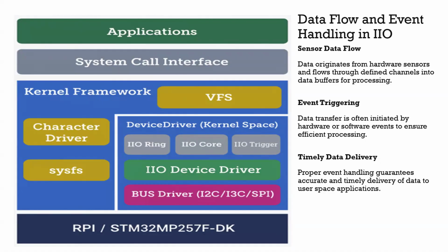One question here. Is the character driver also provided by the framework, or do you have to write and plug it in separately? Yeah, it's provided by the IO driver in this case. But if you want a very generic character driver, you can develop your own, but that takes plenty of time. You have to go through a lot of documentation. But in the IO framework, there is a minimal function, just a few APIs you need to call, and it will enable the character driver for you. But that would be very much device dependent, right, based on which device you are using?